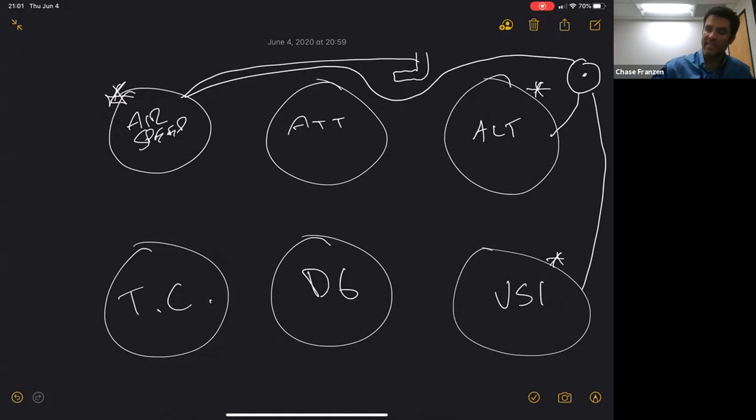You've got a little window called the Kollsman window on the side, as we've seen when we pre-flighted the airplane, and that's just dialing in the current barometric pressure at the field level where your aircraft is located. So at Montgomery, we set the altimeter setting, the pressure at field elevation, and then we take off. It goes from 450 feet to 550 feet, 650 feet, as those aneroid wafers are changing in shape and then changing the mechanical linkages that change the arms on the face.